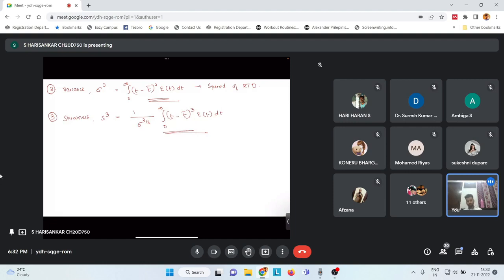Okay, so another thing that you can use as a sort of shortcut for the mean residence time. Let's say you are given a residence time distribution like this, a sort of isosceles triangle, starting at 0 and ending at t. If you are asked to find the mean residence time t bar here, what you can look for is the geometry of the residence time curve.